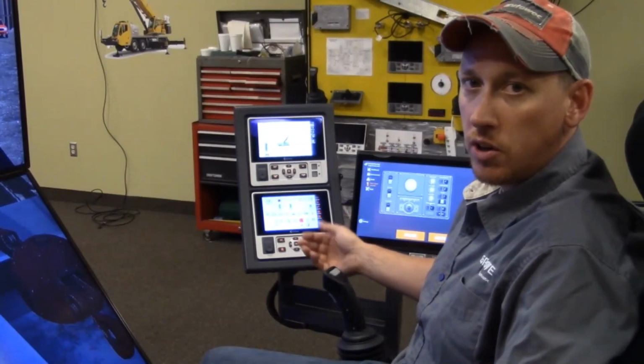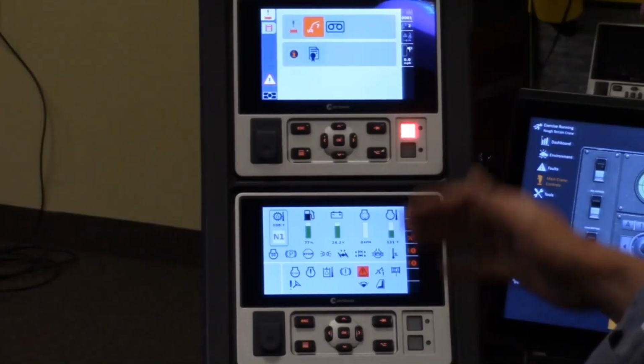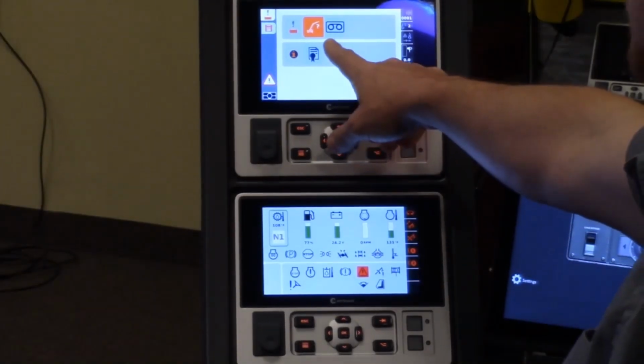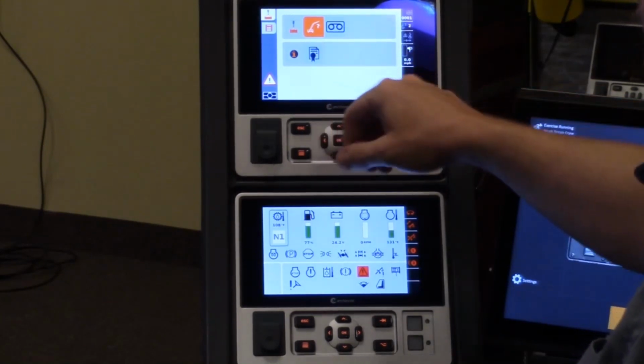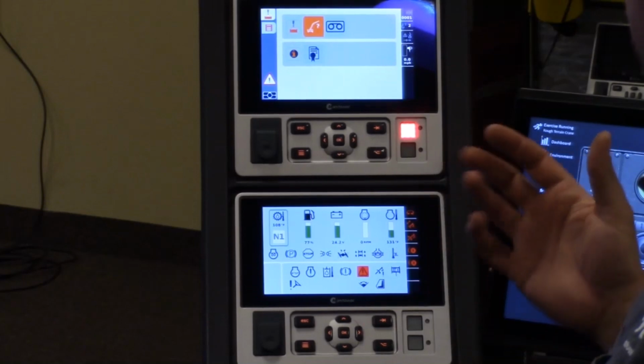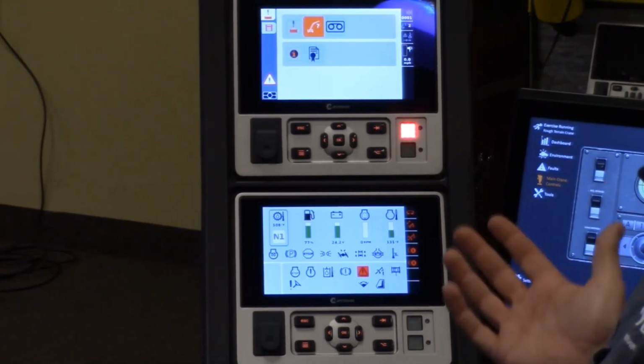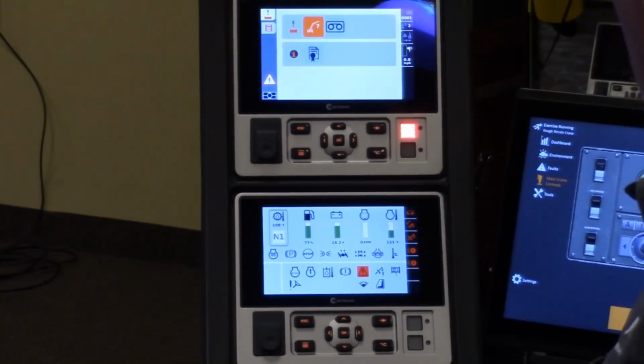So next we're going to be talking about the crane RCL and ODM displays. Once you start a simulation, it's going to ask you to set up an operating mode. This is where you would actually go through the RCL display and tell it whether you have a jib stowed, your outrigger position, things like that. For this, we already have an operating mode set up, so we're just going to look at the main RCL display.